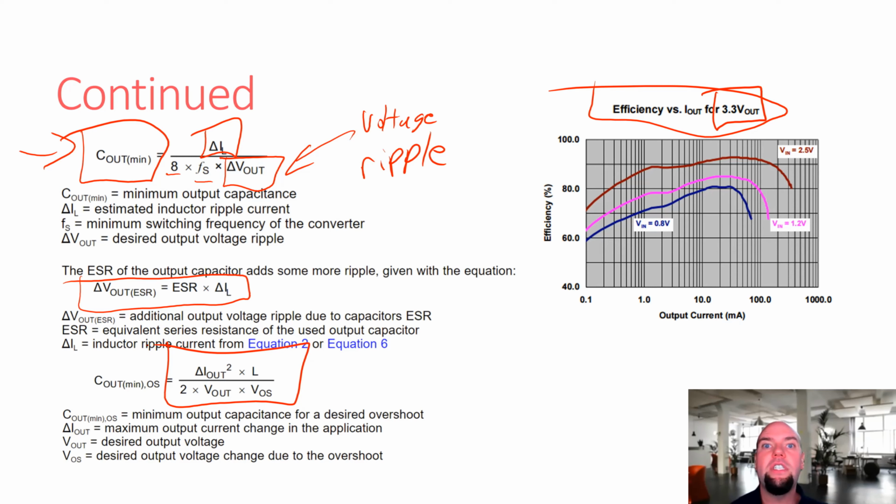These are typically where you'll see these rapid changes in current, and this is where you can have these overshoot issues. A lot of people have this problem where they do a design and say, every time this thing goes to sleep, it restarts. Sometimes they say every time it wakes up, it restarts. What is going on? Those sleep and wake up events are pretty critical events. There are a lot of things that can cause something to go wrong at a sleep or wake up event, but sometimes it's really good to put a scope on your power supply and check those.